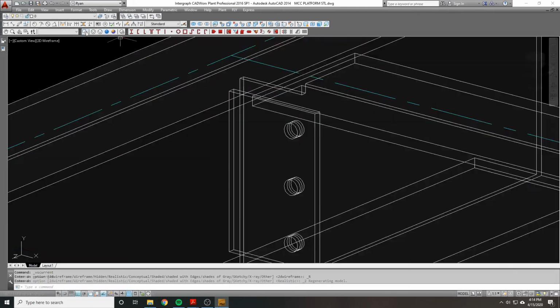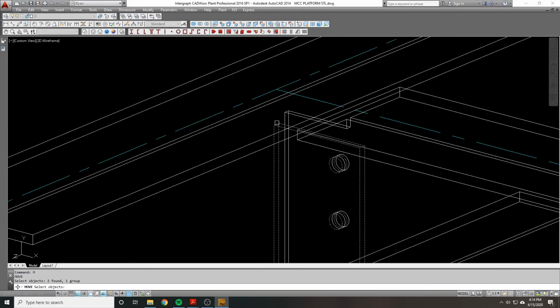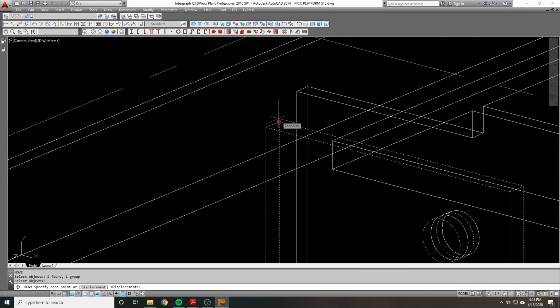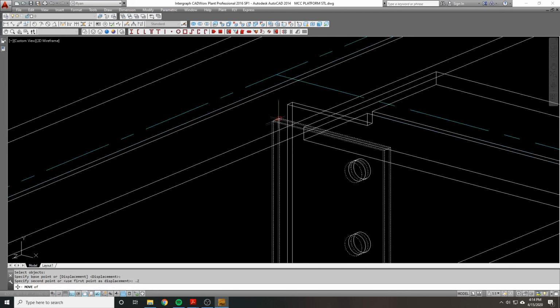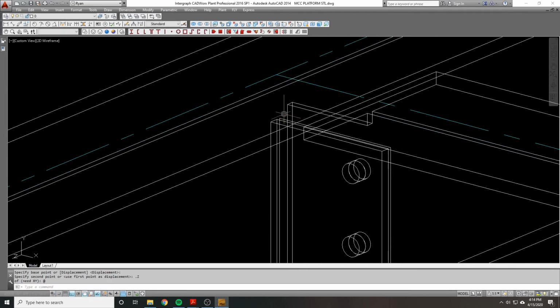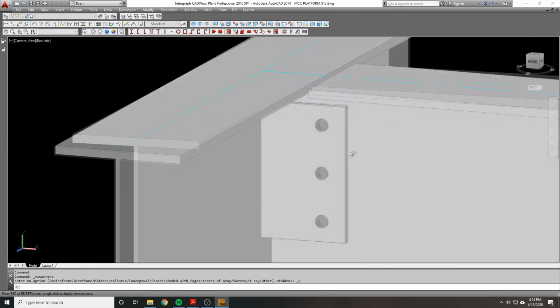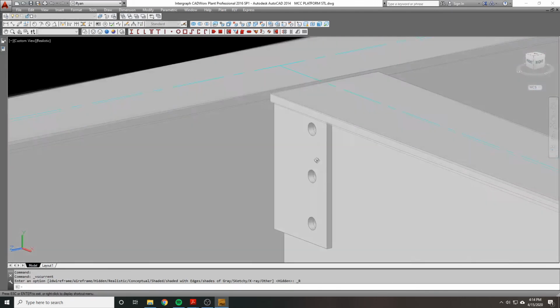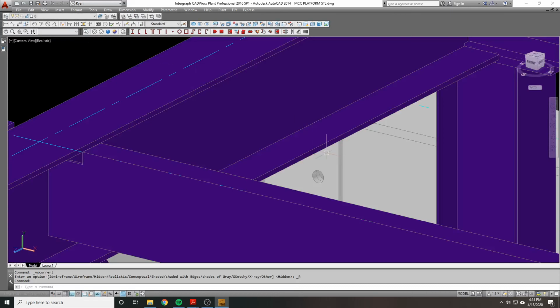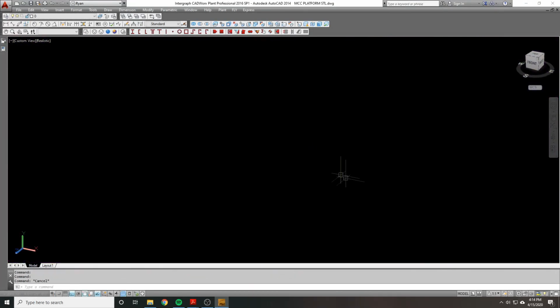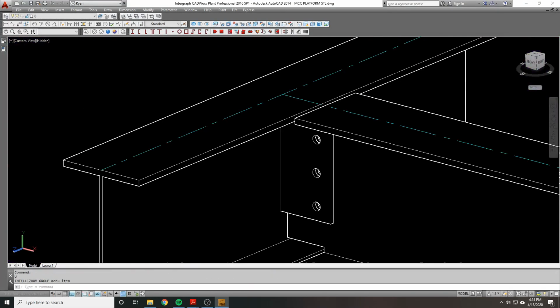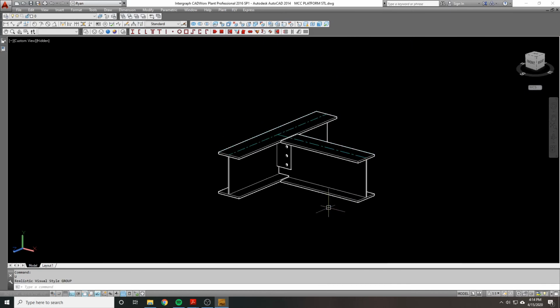That's right. That's the one caveat, is that there's no way to control the dynamic block in the z-axis, so this will have to get moved using a point filter to the face of this beam. And you can see that now it's lined up. That's the downside to using, oops, let me go back. That's the downside to dynamic blocks, is you cannot edit in the z-axis.